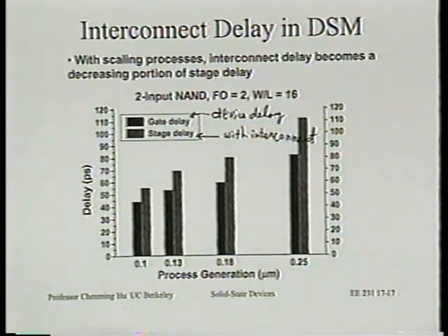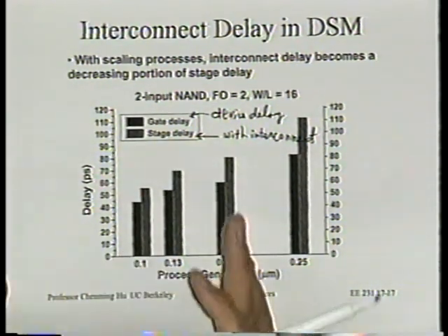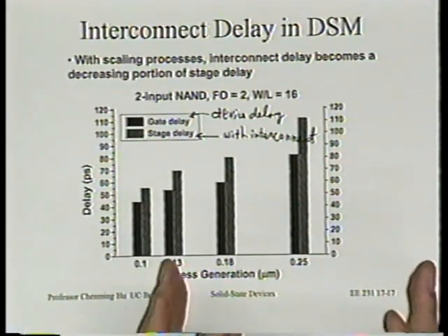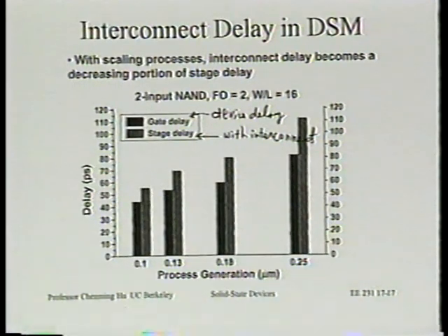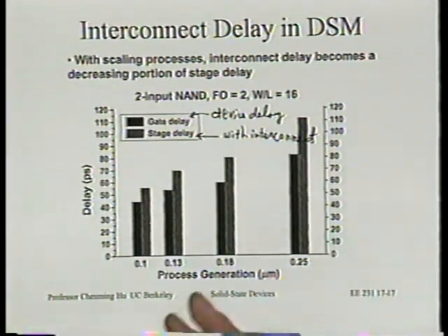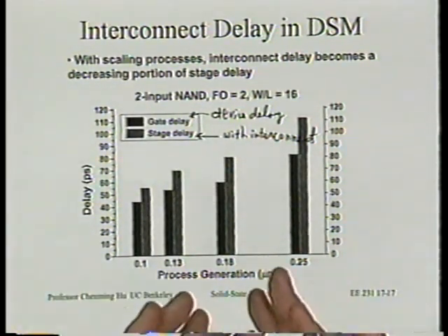It is within one circuit block. One technology design methodology in the future is that the chip will be made of many blocks of circuits. Each block can be an IP block or a fairly large circuit designed by itself. In fact, a whole CPU will be one such block. Each of these blocks, however, probably would only be 100 micron in length. It's not going to be the entire chip. The chip may be getting very, very large. This block probably will not get larger. In fact, it may get smaller because we're scaling things. You see what I'm talking about?